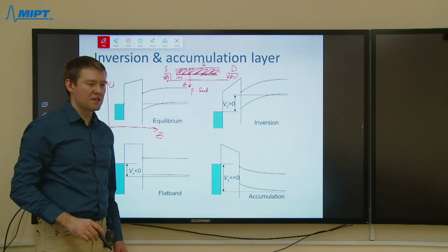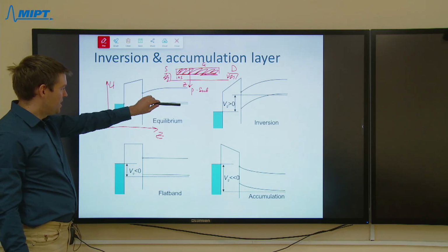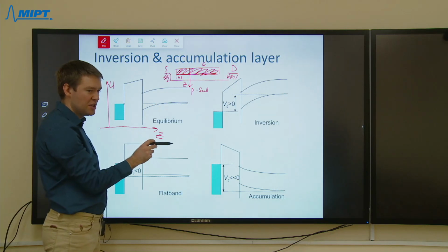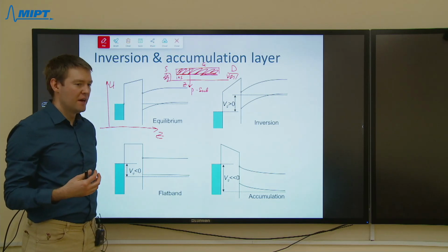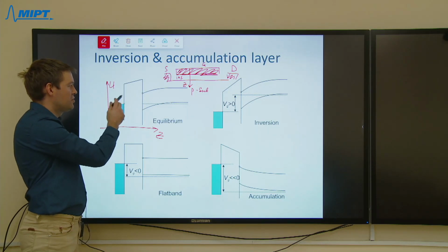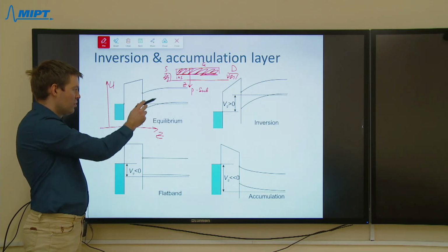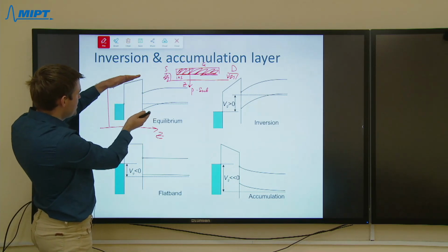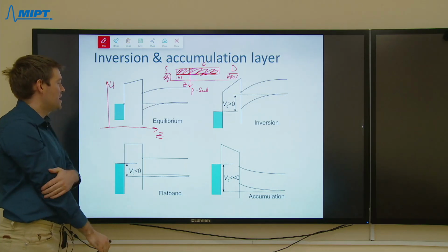When the semiconductor layer is in equilibrium, then it is p-doped in the bulk, which means that the Fermi level is very close to the valence band edge, and from what we know from the Schottky junction theory, holes start migrating from p-doped semiconductor into metal, there is a depleted layer formed where we have a small number of holes and slightly increased number of electrons, and there is a small bending of the barrier in this direction, as I have indicated.